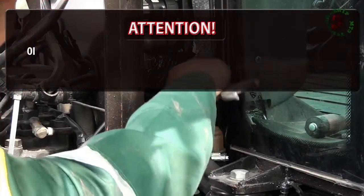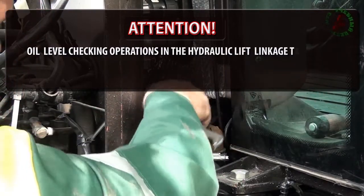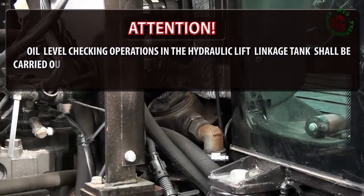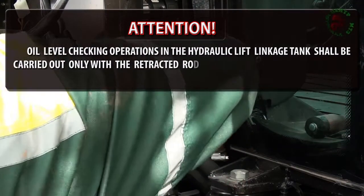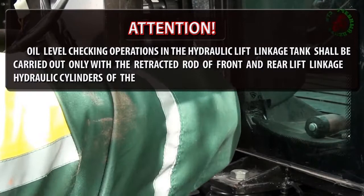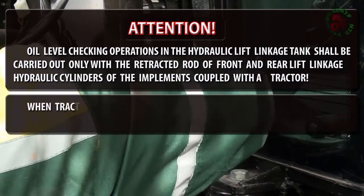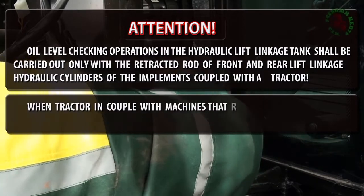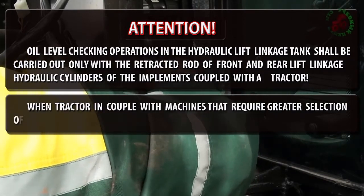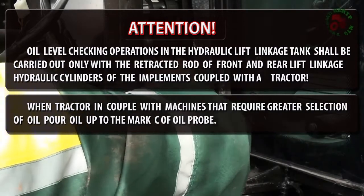Attention! Oil level checking operations in the hydraulic lift linkage tank shall be carried out only with the retracted rod of front and rear lift linkage and hydraulic cylinders of the implements coupled with the tractor. When the tractor is coupled with machines that require a greater selection of oil, add oil up to the mark C of the oil probe.